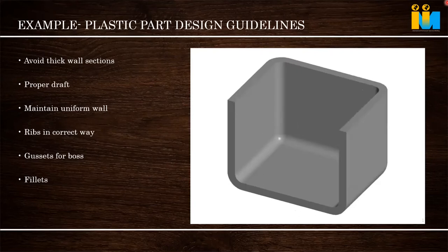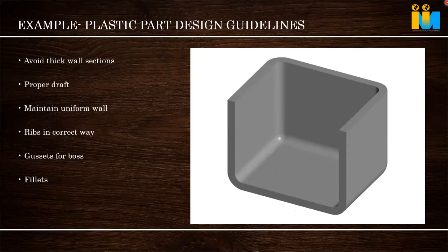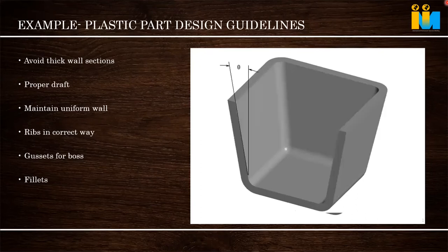It's pretty simple. This is also like this. Now here there is no draft. Removal will be difficult. The part may stick to the cavity side. If it is sticking, and a higher amount of pressure is required for ejection, then molded-in stress will be induced. So what to do? Give a draft. Give a generous draft wherever possible. Don't say half a degree.